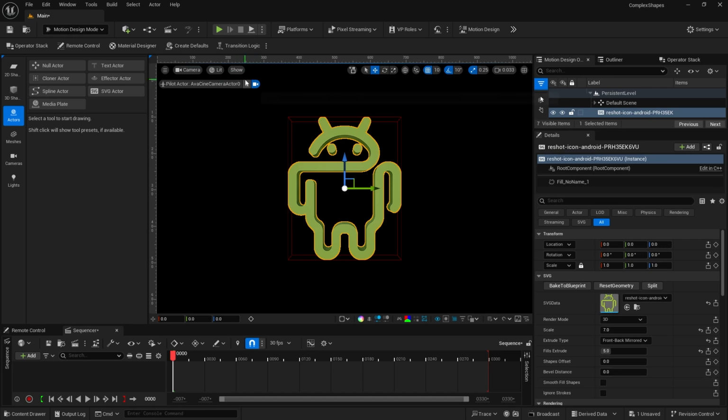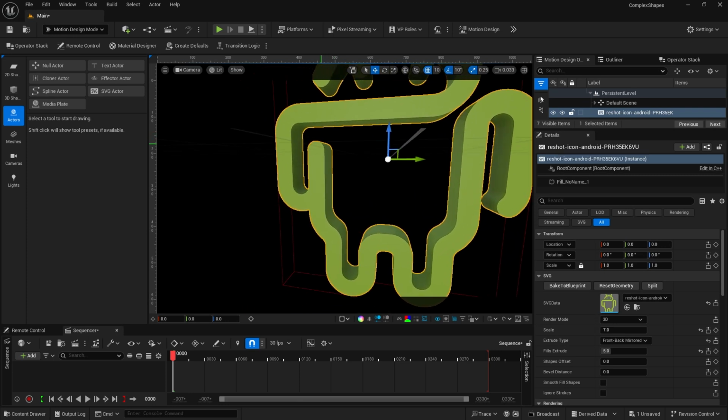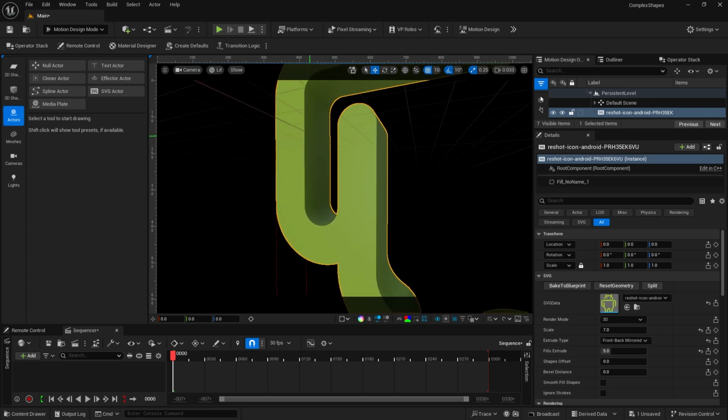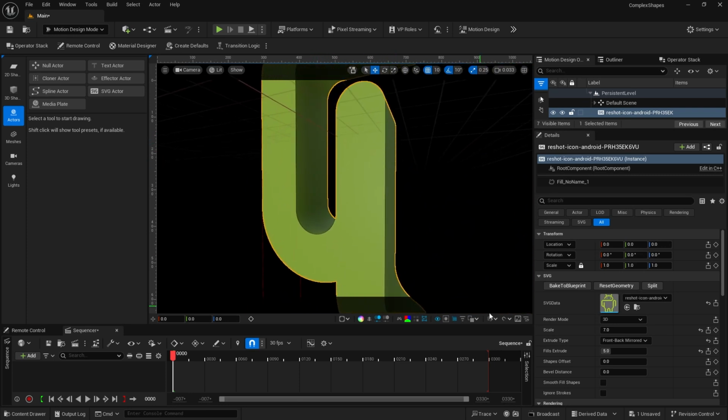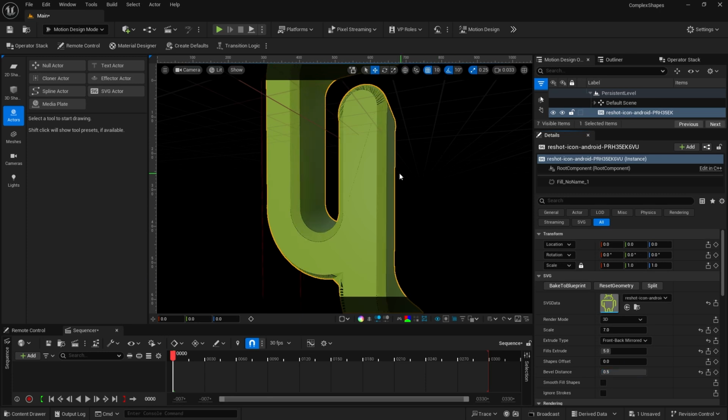I'm going to jump out of the camera and move in closer to the object a little bit. This is going to allow us to bevel these edges here. So if we're not wanting these sharp edges, we have this option. So I'll increase the bevel distance, and you're going to need to adjust that and then let go of it to actually see it render. But you'll see now that we have this 45-degree angle between these two sides. You can continue to increase that up to 0.5 right there. You'll see that we get this displacement, this tearing in the object.